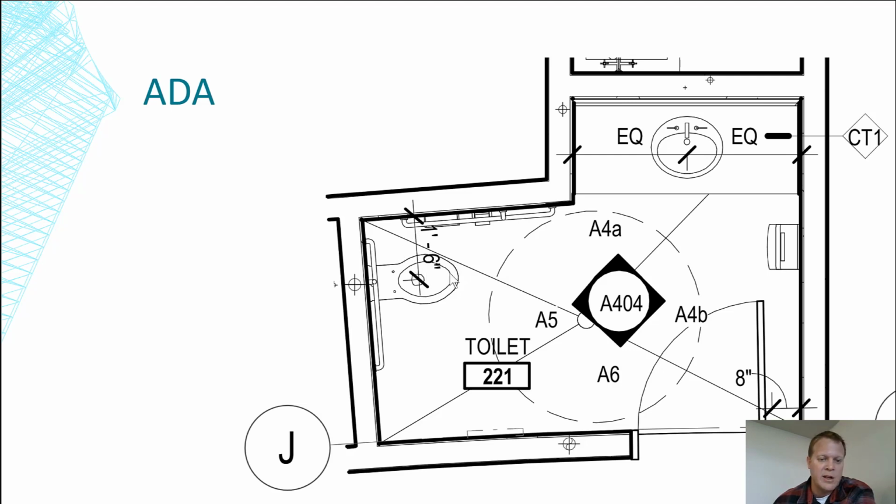Go get yourself a little ADA card. I think you can get them online for $5-10. Little cheat sheets that they sell. You've got to know exactly where this stuff goes. So this is 1 foot 6, and the plumber needs to make sure that this hits exactly right. I need to pull my own little card out and see what the tolerances are. Usually an inch.